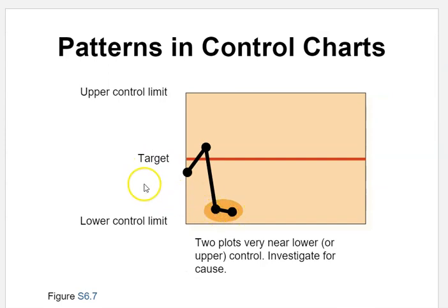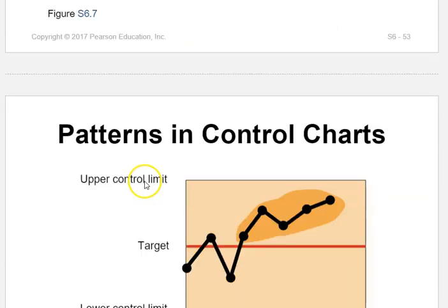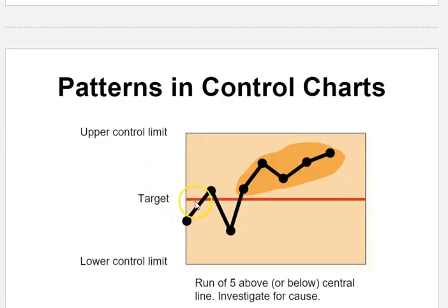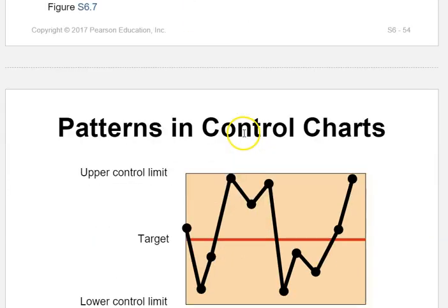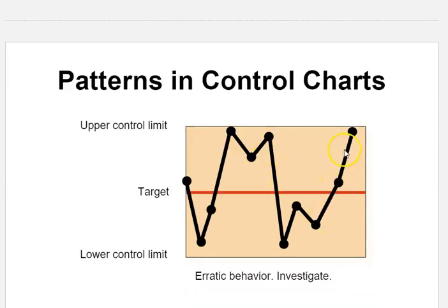This can be a sign. Let's say this red line is the average. You can see that on average they're moving up, right? So instead of having ups and downs, you're having up, down, then up, up. That's showing a pattern of the system going out of control. Same here, three back-to-back, they're moving up. One here, two, and three.